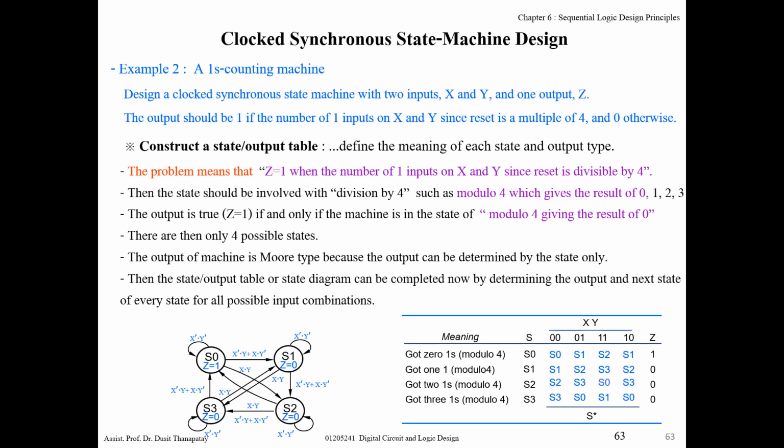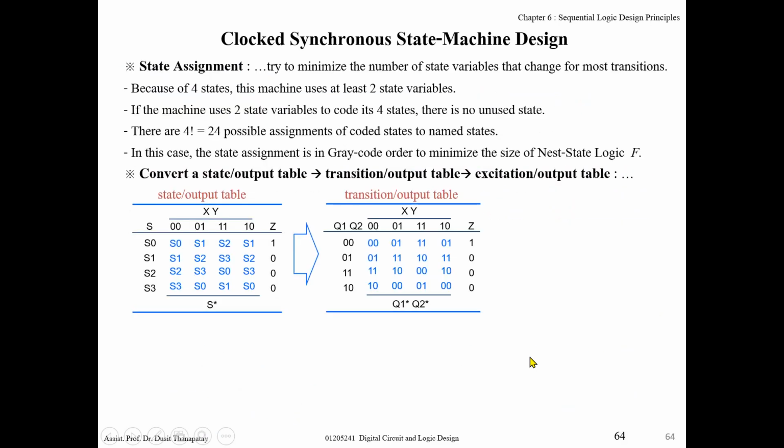Okay, now, from this example, you design by using this state output table. The next step, you must change the state names to binary code, or state assignment.